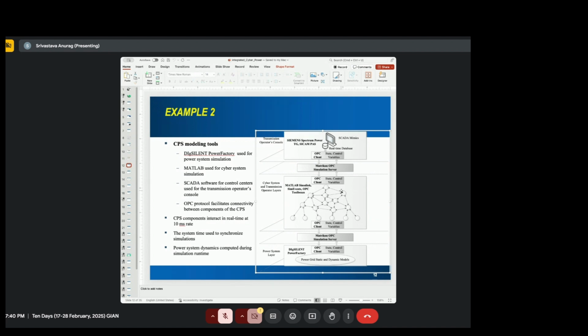with all the nodes in detail. We'll talk about it in a little more detail. It has to be an OPC client, and there will be another OPC client talking with another OPC server, which is delivering the data and taking the data from the SCADA, and which is kind of mimicking the delivery to the EMS, right, or your application. This also has to have an OPC client and then state control variables.